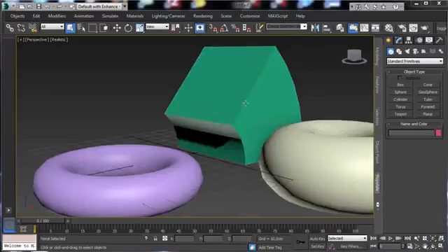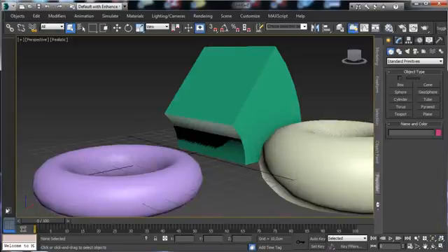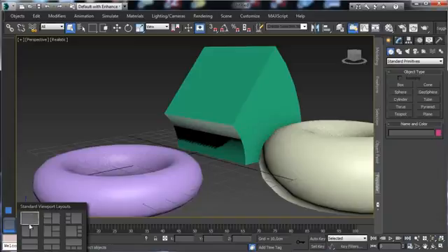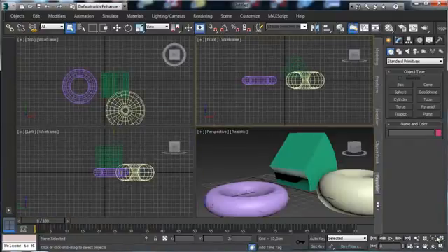So, something more related to the usage of the user interface. There is a really fast way to move between the various viewports. You know that we have the various viewports. We can go and maximize one viewport. You know that we have the viewport layout there to create some different configurations for the layout. But there is a fast way to move between the other viewports. You can press, for example, the shortcut on the keyboard to call, for example, the front or something like that. Or you can exit from this one, select the front and go to maximize.